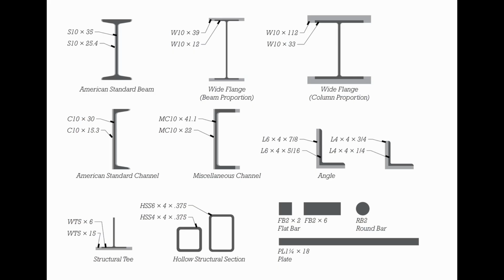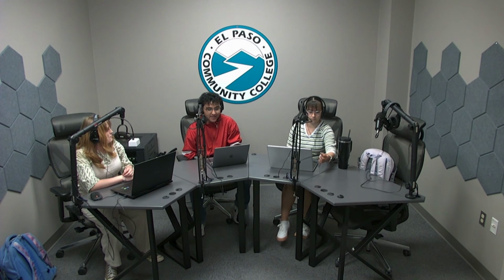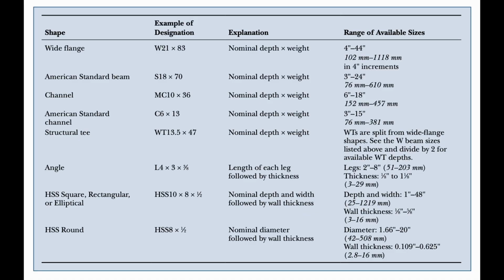I believe I left off on the families of steel shapes and how they can provide architects and engineers with a really good selection of shapes for each member in a building, which can also help avoid waste. The actual shapes themselves are identified using what we call a standard nomenclature. How it works is they begin with a letter for the shape, followed by one or more size, thickness, or weight dimensions.